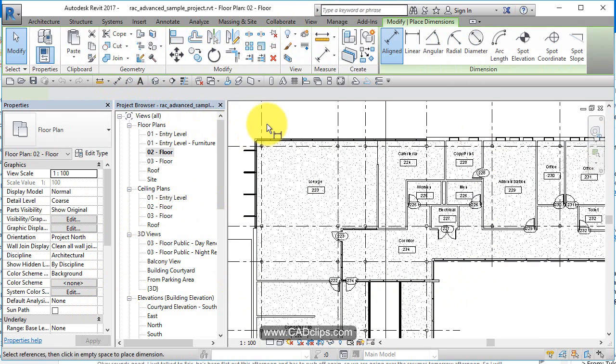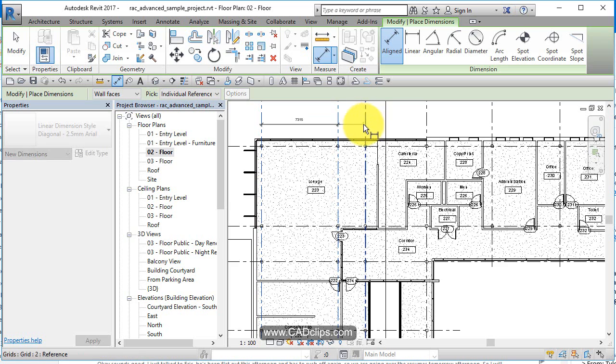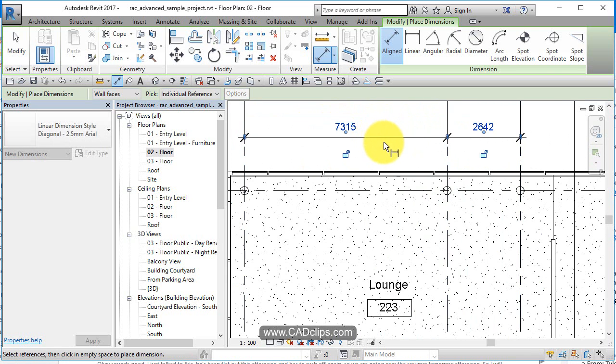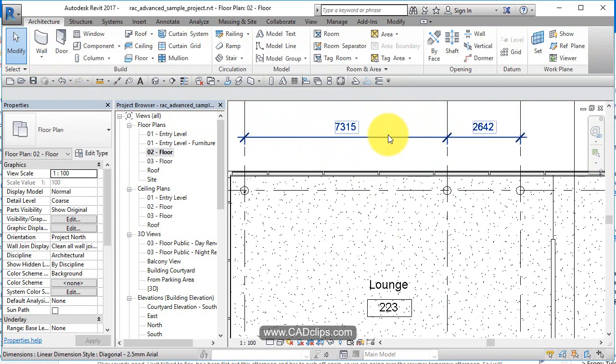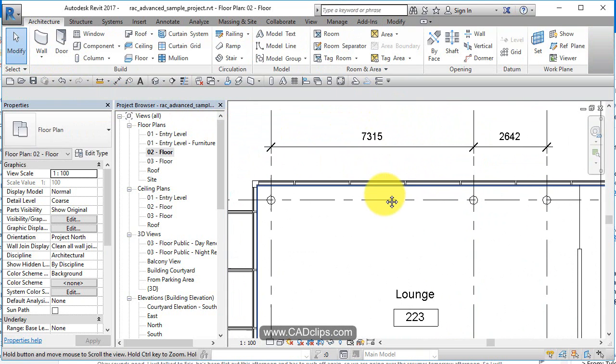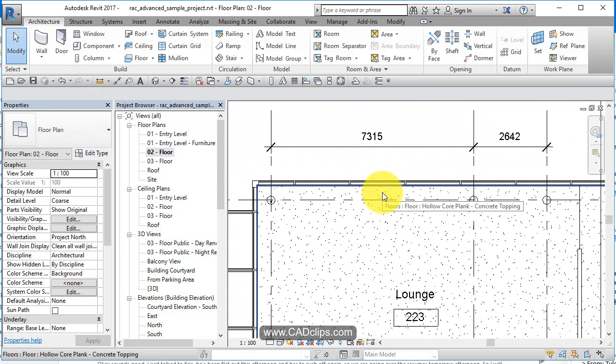That's because right now our project units are set so that area is in square meters. If I go and add a dimension in over here, and then zoom in, and I click to place it, and then I hit modify or escape, we're seeing millimeters. Now, there's the global project setting, and then there's individual overrides. Just because the project is set to be metric doesn't mean my dimensions have to be metric or my area has to be metric. I can have a metric project with imperial dimensions and vice versa. So you can mix it up all you want, and it works really quite nice.